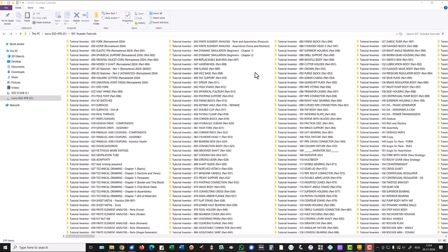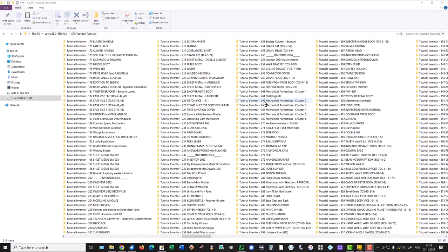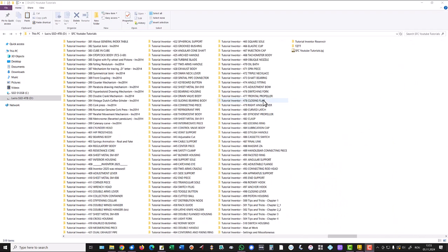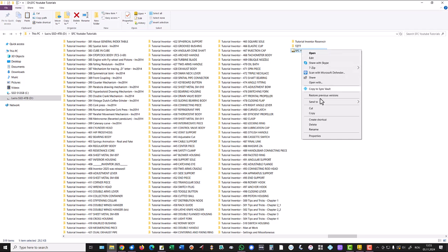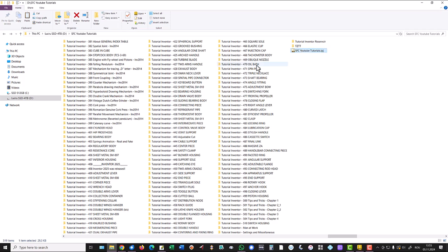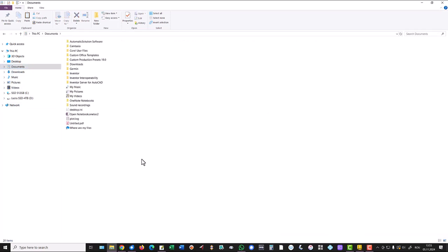An interesting aspect of working with Inventor is as follows. Here I have all the 500 tutorials, and you see here a special object, YouTube tutorials.ipj. You can copy this object, for instance here in Documents, paste.